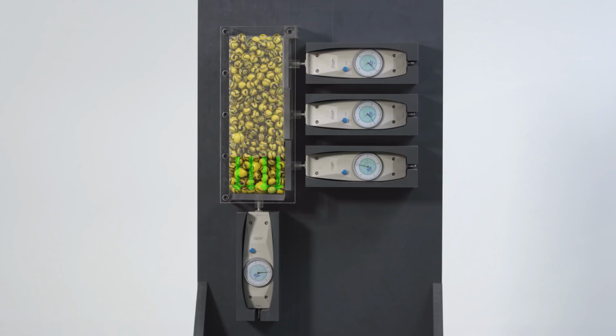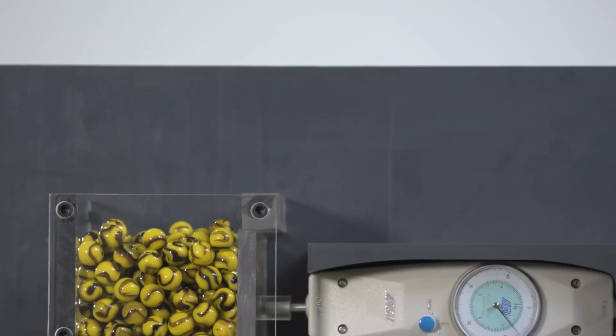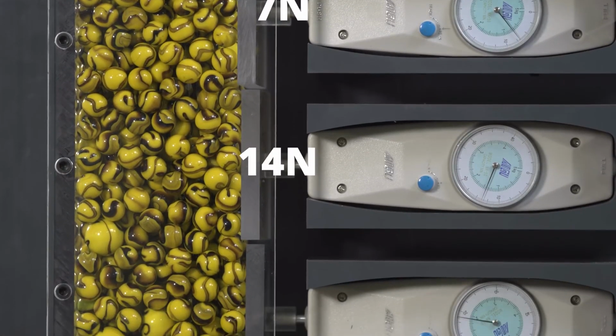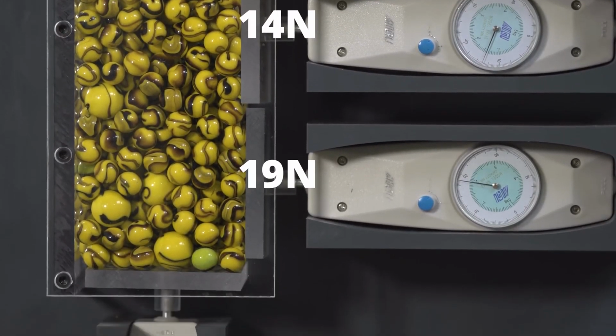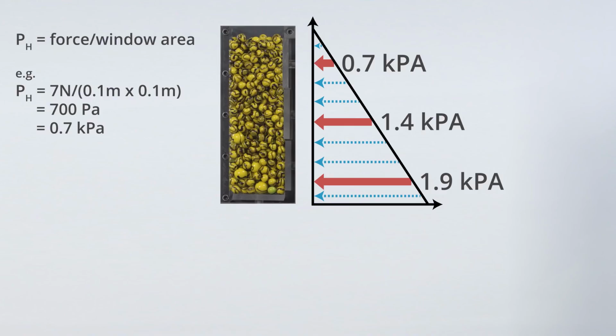When the chamber is filled with marbles, an example of a granular material, the indicated horizontal forces are 7, 14, and 19 newtons, and the downwards force on the bottom window is 33 newtons. And it is easy to see that the corresponding horizontal pressures do indeed increase linearly with depth.